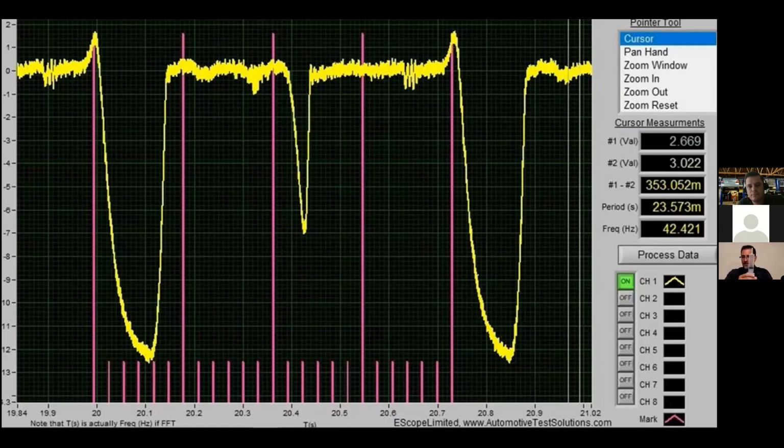However, if we go back to my PowerPoint, we don't close it here, do we? We don't close it at 60 or 90 or 120 or even 150. We close it at about 170. So if this represents 180 degrees of crankshaft rotation, and there's 90, and there's 120, and there's 150, and there's 170, how much stroke do I have to build compression? How much pressure can I build by moving the piston that much? It looks to be about 2 psi here.